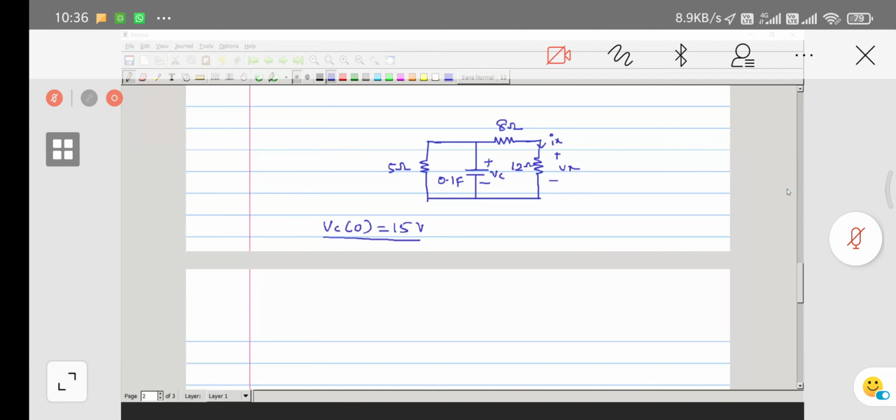So here, this capacitor is acting as a voltage source and it can deliver energy, but it cannot do so indefinitely. This capacitor can deliver energy for a short period of time. The capacitor has some capacity, and depending on this capacity it can store some energy. So it can deliver the energy to some external circuit up to some time. It cannot deliver the energy to an external circuit over an infinite interval of time. That's why we call it a source free RC circuit.